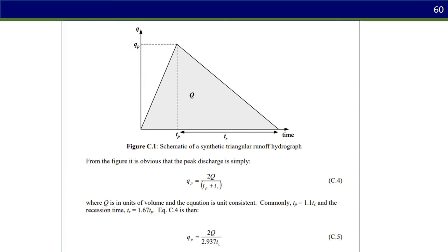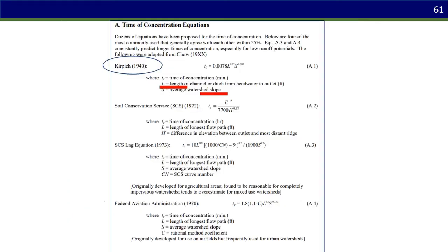One of the things I also want you to take away from this is that there are lots of ways to calculate these things, right? That was a super simplistic hydrograph and a super simplistic way of calculating time of concentration to understand the concept. So we have an equation that we can apply. We run that in a Python script, or we can even code it directly into an ArcMap project.